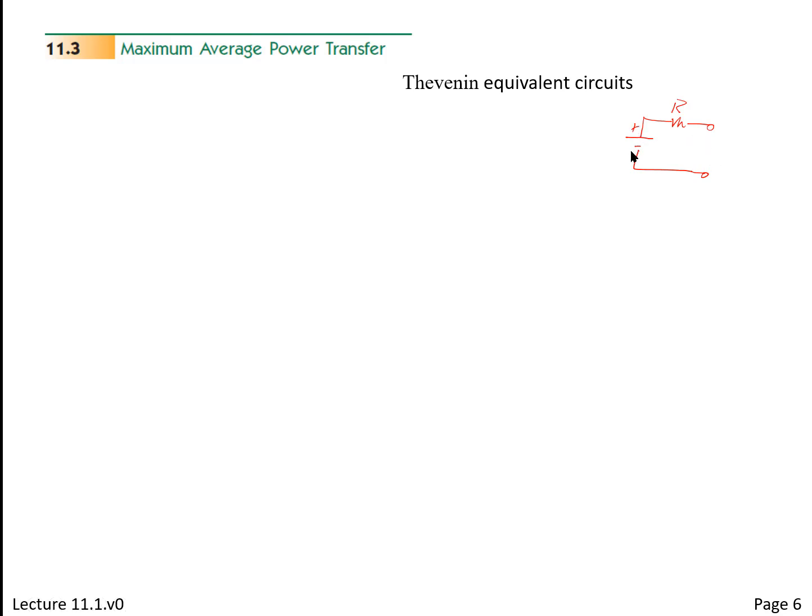And I say, well, how much power will get out here? How can I deliver the most? I'm doing this strictly in terms of DC now, right? If I want to get the most energy out here, how do I do that? You might have to go back and refresh on Thevenin equivalence, but it happens when you put a load that's equal to, this is the load, and this is the source. When our load equals our source, I get the most energy out.